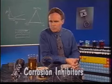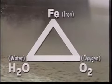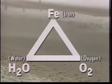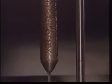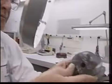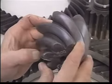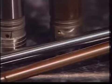Inhibitors are needed to protect against rust and corrosion caused by the attack of oxygen and acidic byproducts on metal surfaces. Normally, the rust and corrosion rate is low, but it increases greatly when unprotected metal is in the presence of water and oxygen. Unfortunately, these elements are present in abundance in internal combustion engines. Rusting, the oxidation of iron, can cause frozen hydraulic lifters and stuck oil pressure relief valves. And it can actually destroy engines, transmissions, the final drive gears, and bearings. By forming a protective film on metal surfaces, rust inhibitors provide a barrier between the metal and the rust-causing moisture and oxygen.